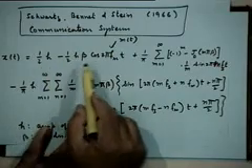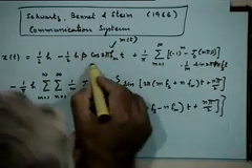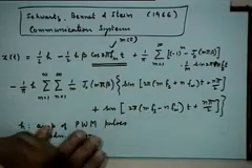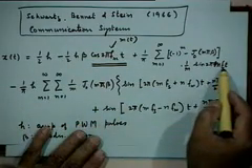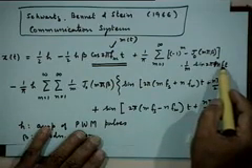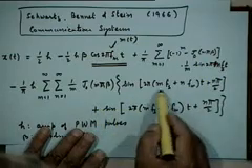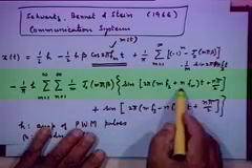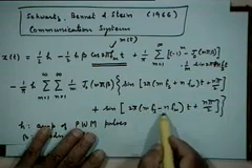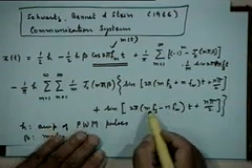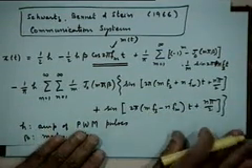Now let's see whether there is any method in this madness. What you will notice is that this signal has a DC component, has the desired message m(t) as one of the additive terms, and then has components corresponding to the sampling frequency of the pulses, as well as sum and difference frequencies, m fs plus n fm and m fs minus n fm, for all possible values of m and n.